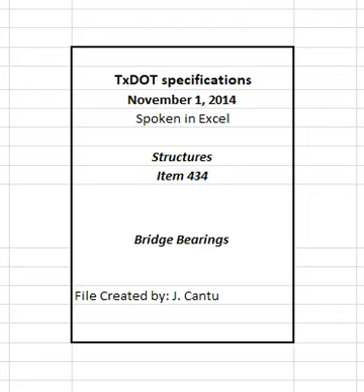3.2.2.1 Lower Component. Manufacture one additional bearing lower component per project for testing purposes. Notify the Construction Division, which will sample a bearing lower component at random from the lot after bearings have been manufactured for a project. Forward selected samples, freight prepaid, to the Construction Division, or to their contracted testing laboratory when directed. Lower component samples will be tested to the following. TxDOT, Part 2 Adhesion Test Method 2. Adhesion between the PTFE material and steel plate must meet a minimum 20 pounds per inch.